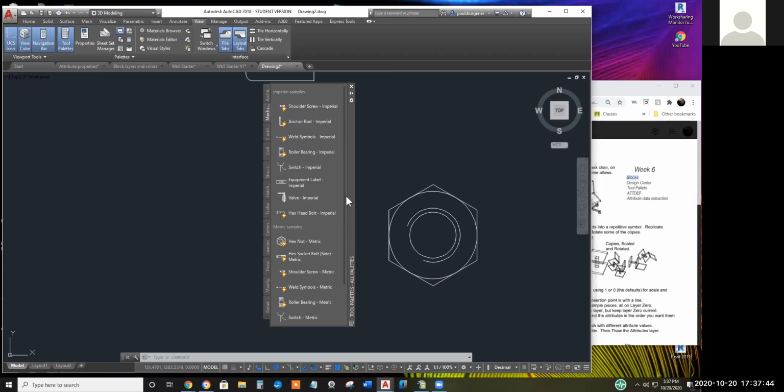But for mechanical, if you type in screw, it opens up a library and it asks you if you want a panhead screw, a socket head cap screw, and then it'll ask you what the thread is, let's say 3/8-16, and then you pop it into the view, and then it'll ask you for the length, and then you could specify the length. It also has a tapping feature, like if you wanted to show a cross-sectional view of a hole showing, for example, your drill hole and then your tap hole, they're 2 different diameters.